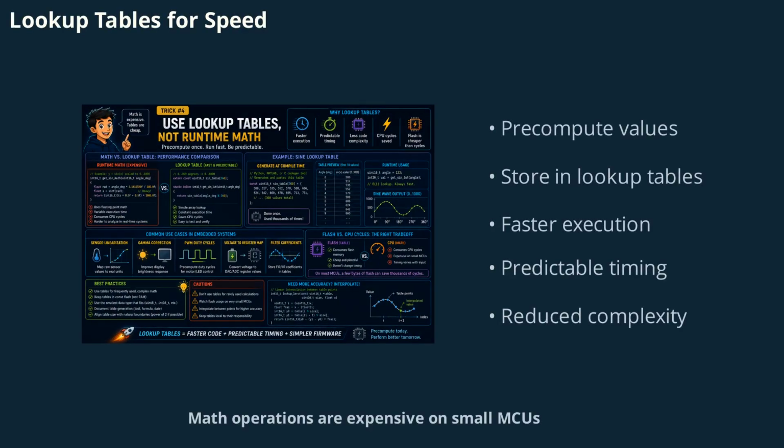Math operations are expensive on small MCUs, especially without a floating point unit. Pre-compute values at compile time and store them in lookup tables. This approach is common for sensor linearization, gamma correction, PWM duty cycles, and voltage register mappings.